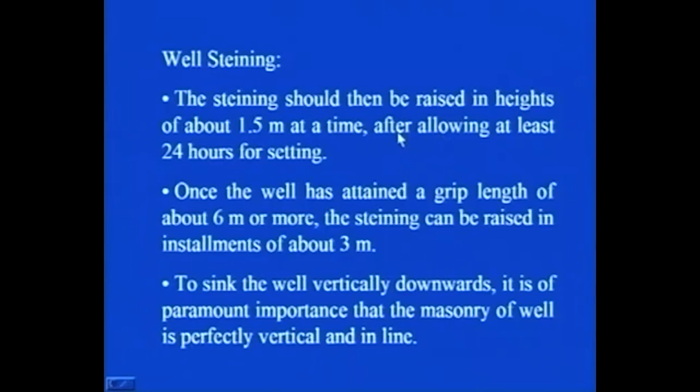Once the well curb has been sunk to the desired depth, then only the steining should be raised in heights of about 1.5 meter at a time after allowing at least 24 hours for setting. So, in one go you should raise only up to 1.5 meters.